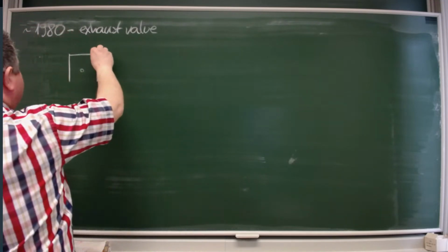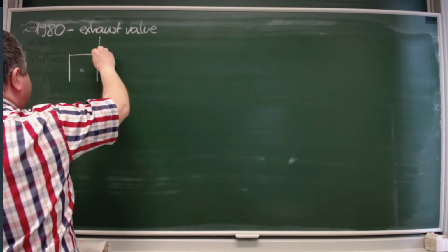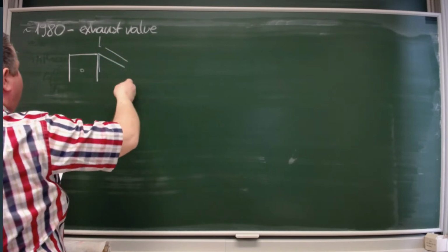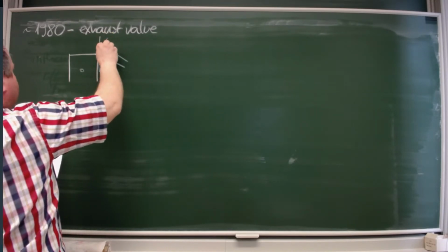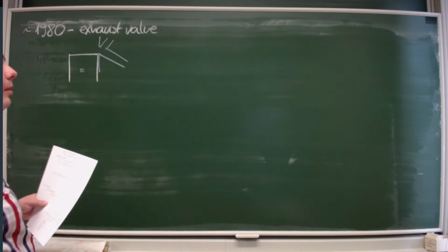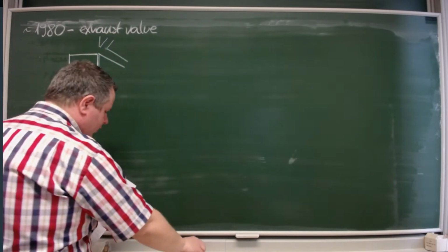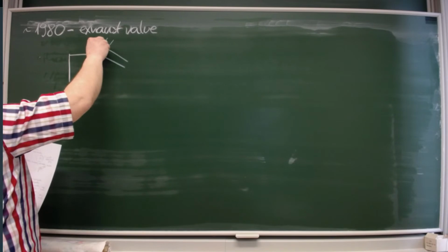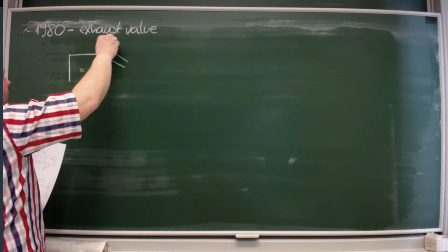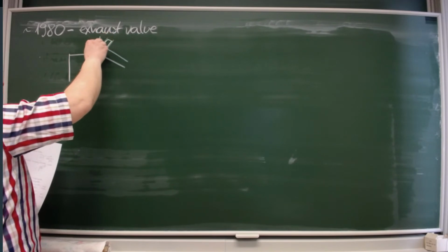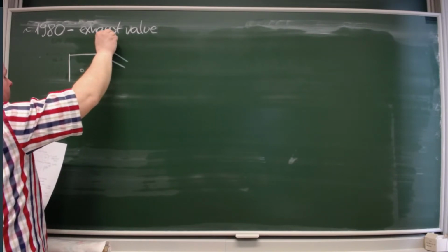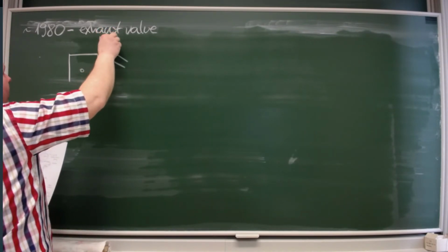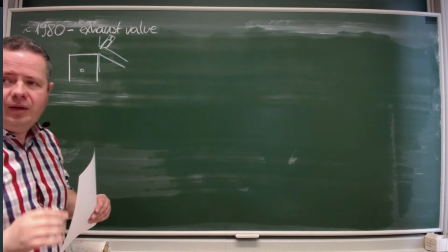You get an exhaust port in the cylinder that starts at a given height, and then you add something here. What you add is a vane, a closing vane that has this shape. It's like a wedge. It can be controlled either by springs, let's say it's controlled by spring, or other mechanisms, cables or an electric motor. You get examples for all of these.